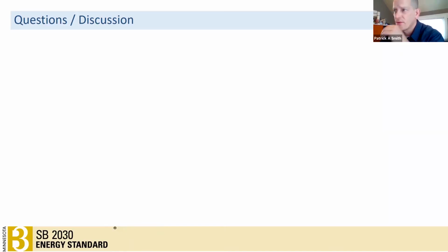The question in the chat was if a project pursues the energy modeling option using the online analysis tool, is the project still required to meet the prescriptive requirements of ASHRAE 90.1 2019? If you pursue energy modeling, I mean, I'd have to meet code, but if you're pursuing energy modeling and we're working with your project to determine what that 12-year package is, then you wouldn't also need to meet ASHRAE 90.1 2019. You're likely going to get a bit more aggressive than you would with ASHRAE 90.1 2019 if you're pursuing that approach, but it's not required.